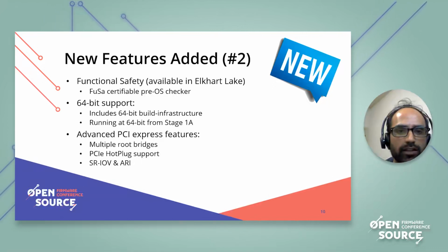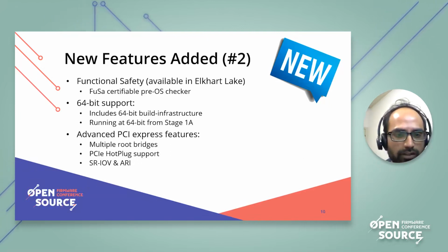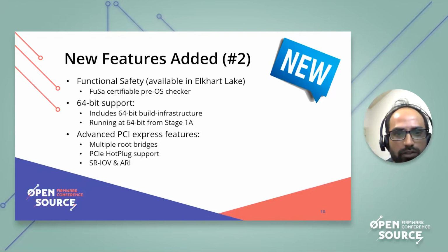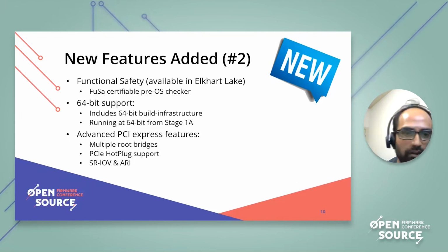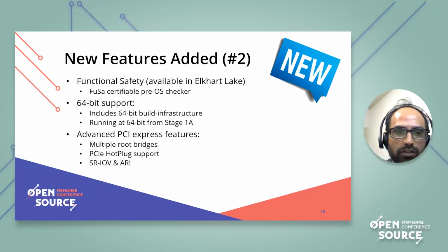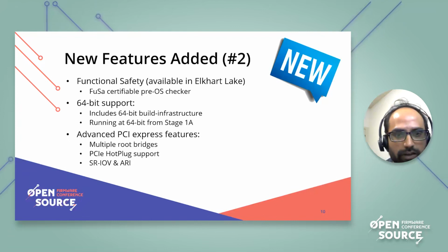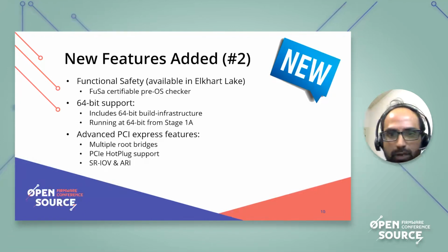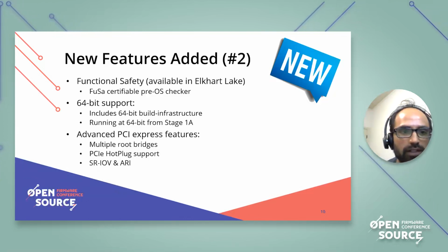The pre-OS checker itself comes in the form of a binary and is not a part of Slim Bootloader, but Slim Bootloader has support to load and launch this kind of pre-OS checker, and then upon its success, automatically fall back to booting your traditional OS. Now, this pre-OS checker can be FUSA certifiable, and it is currently available on the Elkhart Lake platform. I guess Yah Wen can give you more details about this if you have questions.